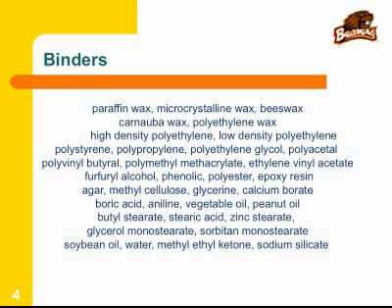I think either a fluorinated polymer, like a Teflon or a modified Teflon, would be appropriate for something like that, or high molecular weight polyethylene with a fluorinated surface. Polyethylene I used the last time. The reactor was blasted. I don't know what happened with that, but I was worried because I need to make another one. Okay. You can try either one.